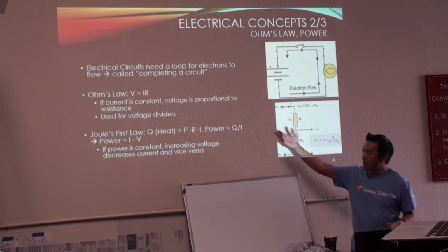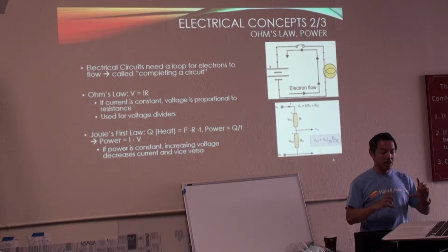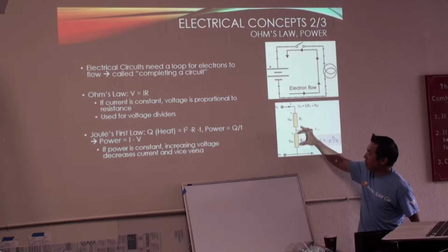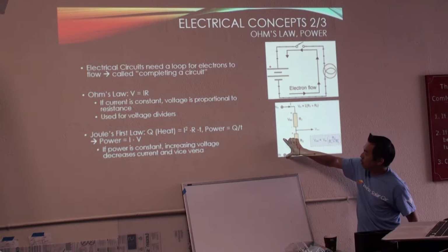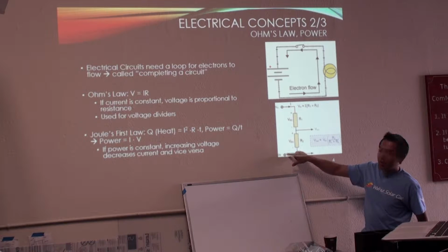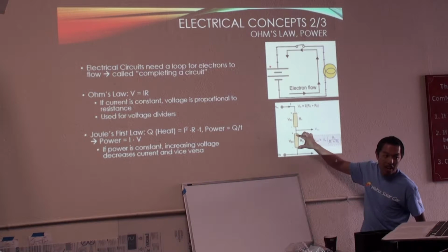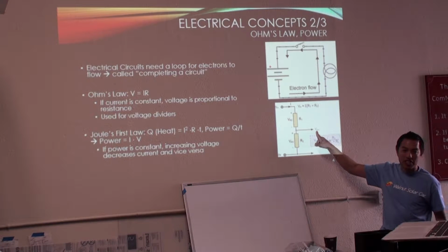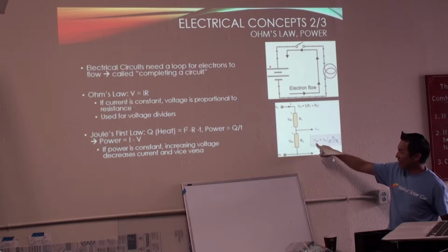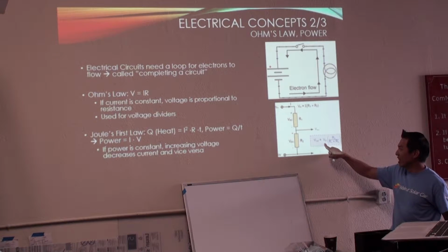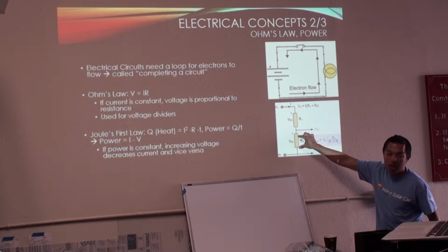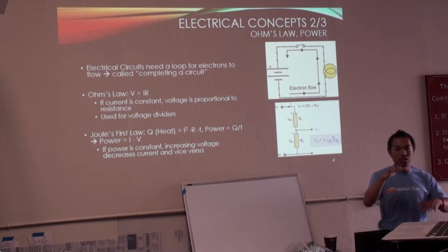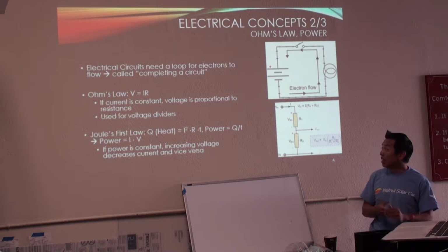The way you can do that, because of Ohm's law, is you can actually divide. You can put, like in here, 2 resistors, and this would be 12 volts there. Based off of the resistance that you have here, you can then adjust the output voltage. So the calculation is the output voltage is the resistance of this bottom part divided by the sum of this, basically percentage of this over that. And that's how you scale voltage. We'll have to do that.